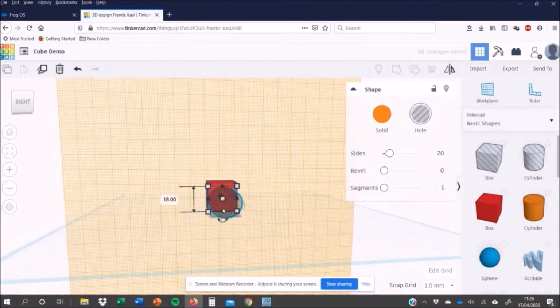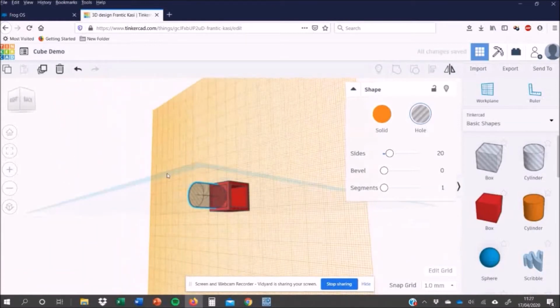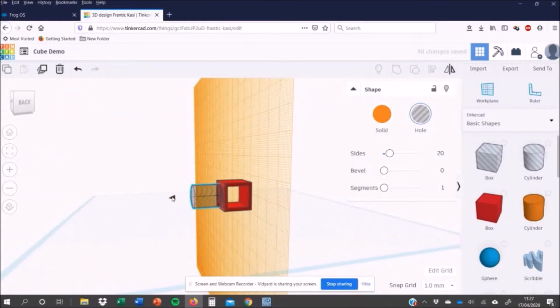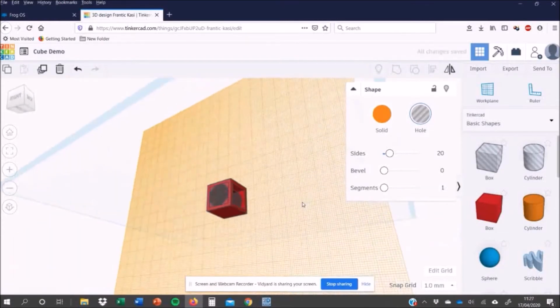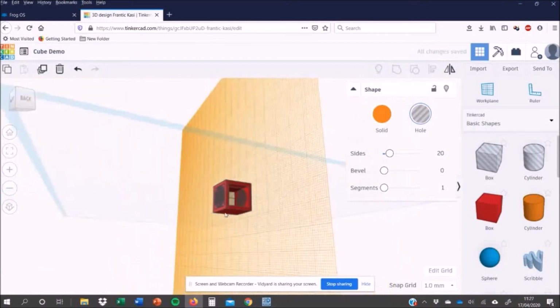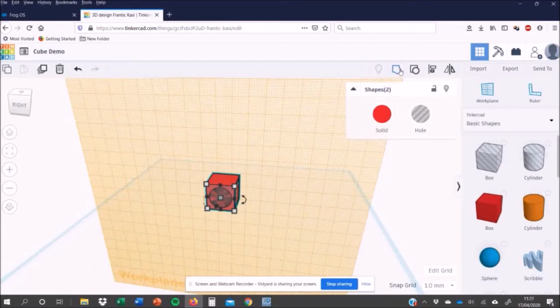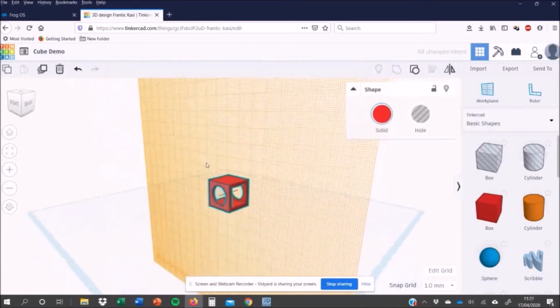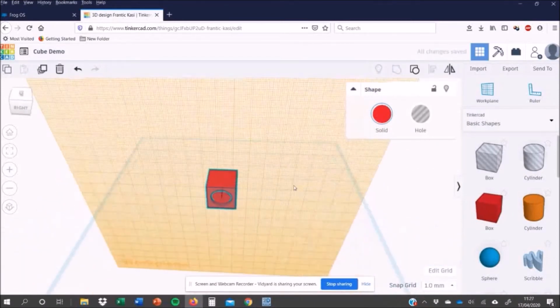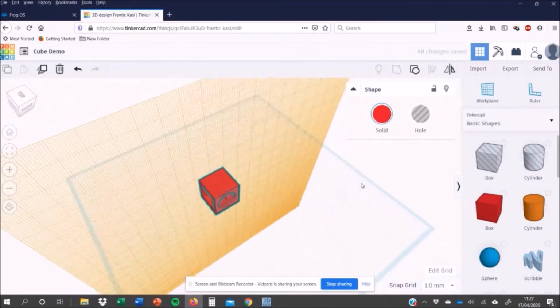Sorry, 2 millimeters. This in by 2 millimeters. This in by 2 millimeters. And that in by 2 millimeters. Okay. And again, I'm going to change its position so that it lines up correctly with the cube. Then I'm going to select all my objects again, group them, and hey presto, we've now cut a circle through the cube. Okay, one last shape to do.